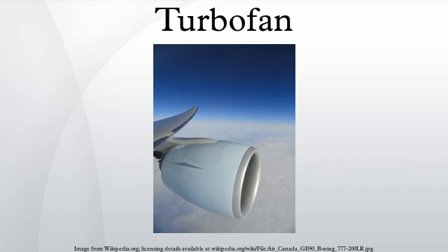All of the large American turbofans feature an IP compressor mounted on the LP shaft and driven, like the fan, by the LP turbine, the mechanical speed of which is dictated by the tip speed and diameter of the fan. The Rolls-Royce Bravo 715 is a non-American example of this. The high bypass ratios used in modern civil turbofans tend to reduce the relative diameter of the attached IP compressor, causing its mean tip speed to decrease. Consequently, more IPC stages are required to develop the necessary IPC pressure rise.